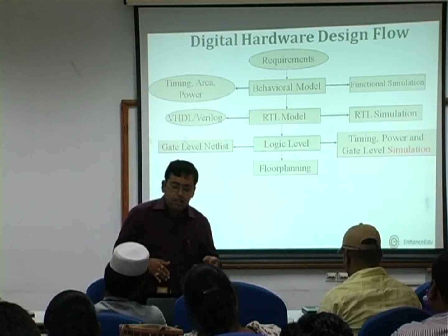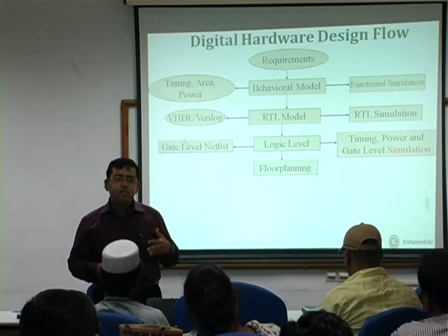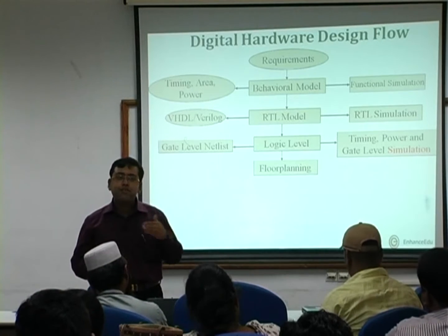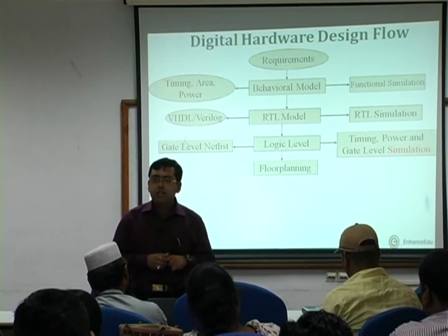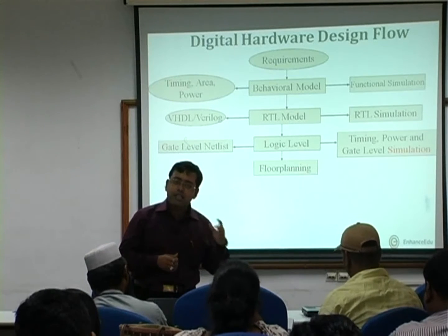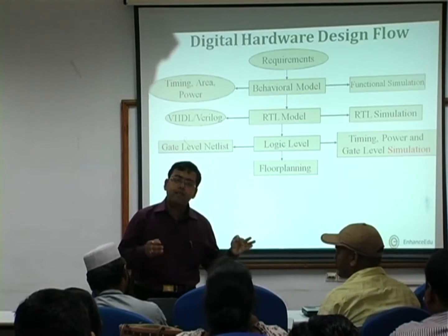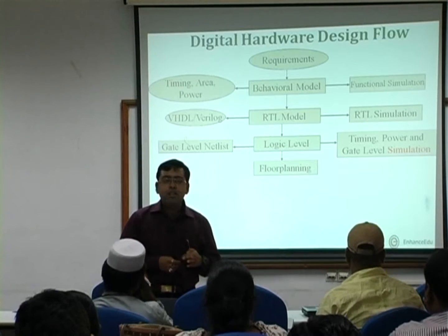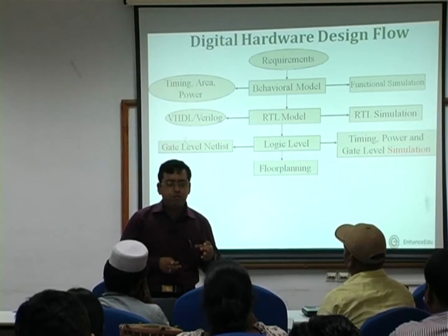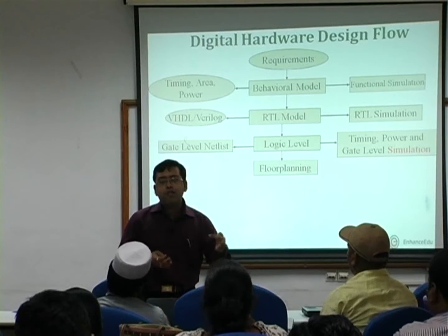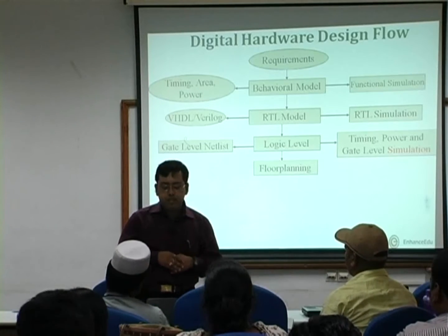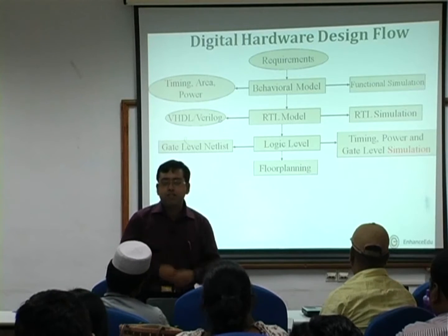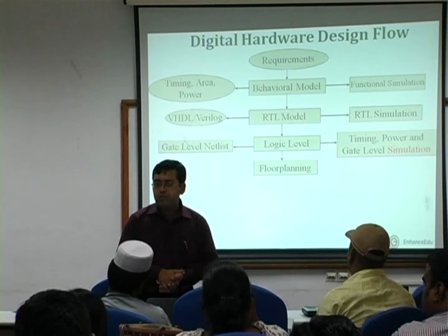Now normally in a digital design flow, since the transistor level design of the circuit is very regular, that means for a particular design we know how we can implement the circuit by an interconnection of transistors. Normally in a typical CAD tool flow, we directly go from the logic level to the physical level or layout design process.